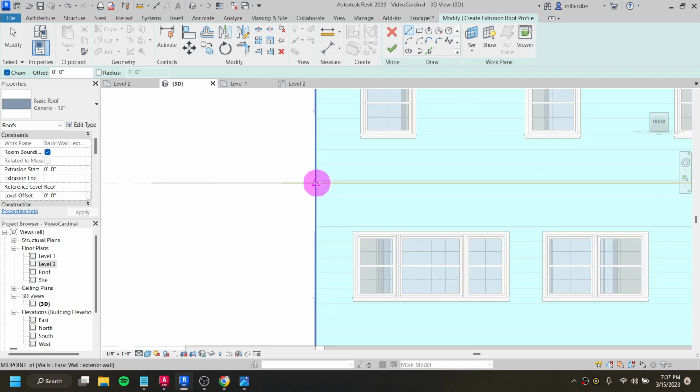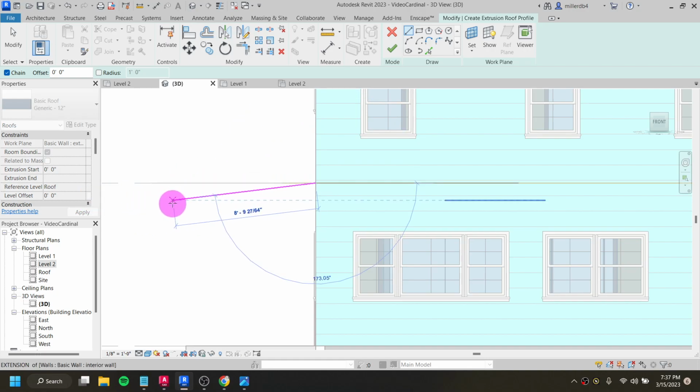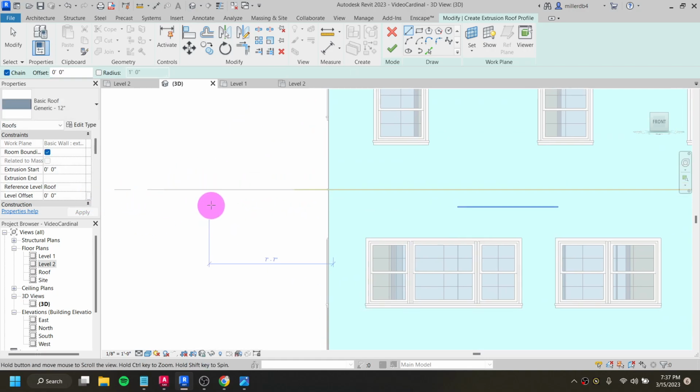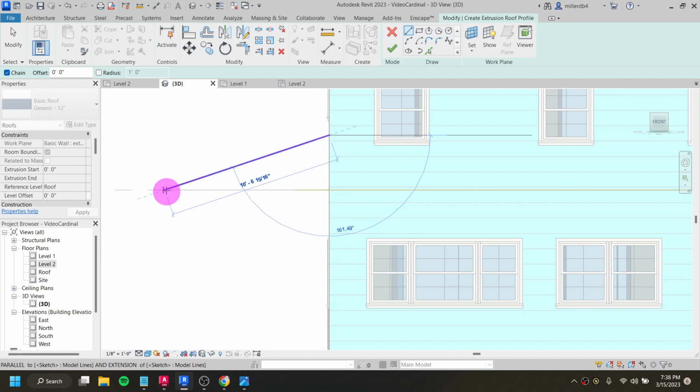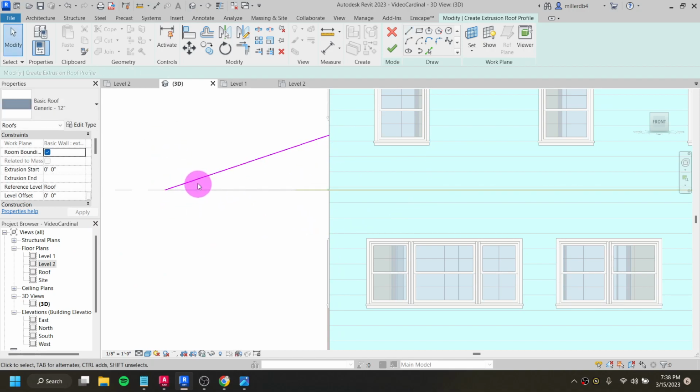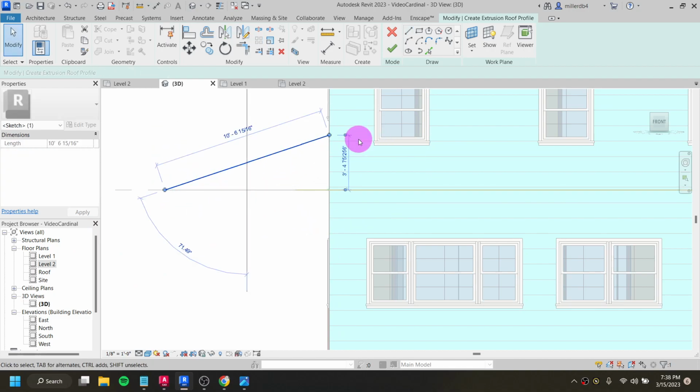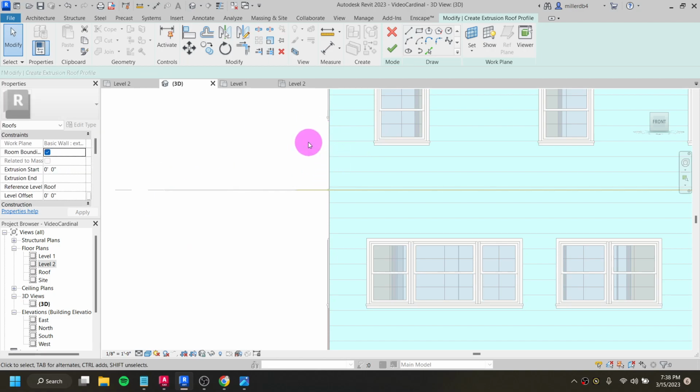And what I'm going to do is put myself into the front view, or just put myself completely parallel with this, and draw a line straight up. I need to make sure I'm getting my slope as 4 feet, because I want it here. In reality, I also could just slope it so that as long as it's not sitting in front of those windows. Because I want a 4/12 slope, and I can't necessarily define a slope like that in an extrusion, which I definitely didn't do when I made my original one. So instead, let's just do it that way.